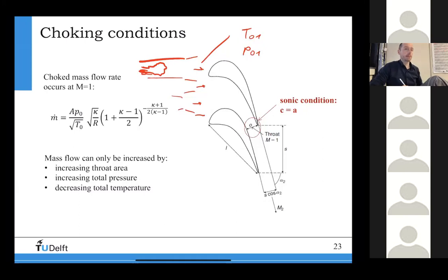Let's say in the combustion chamber, you know how high the temperature will go, and the pressure is given by the compressor, for example. Of course, you will have pressure losses that maybe will change it, and you also have maybe some non-negligible effect of kinetic energy. But most of the time, the combustion chambers are quite big, so the flow velocity inside the combustion chamber, determining the kinetic energy, is so much smaller than the enthalpy. Enthalpy is usually much higher than the kinetic energy.